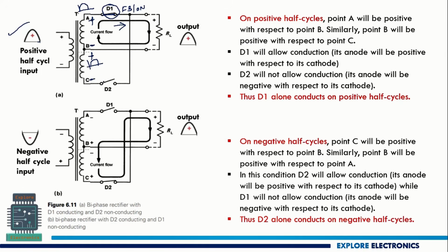And this D2 diode will be having PN regions like this. The negative terminal, or the P region, is connected to the negative voltage. So this is off, or reverse biased, we can say. Because this is off and this is on, the current is flowing in this direction, through RL in this way and comes back to the negative terminal like this. So this region will not conduct any current. So across RL, if we measure, this is the direction of current flow and this is the voltage we are going to get, as we see on the input side.